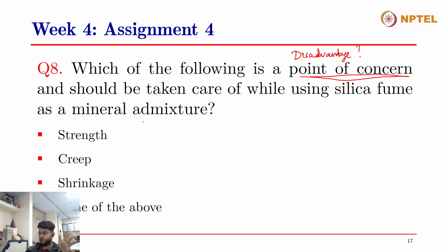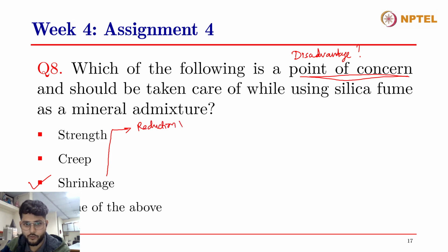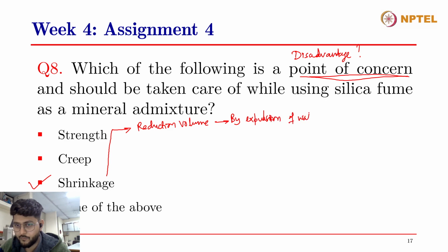Shrinkage is the reduction of volume, right? Right. So the correct answer is yes, it is shrinkage. I'll just mention what is shrinkage: reduction of volume. Now, how does the volume get reduced? How does the volume get reduced by shrinkage? By expulsion of water from the capillary pores.